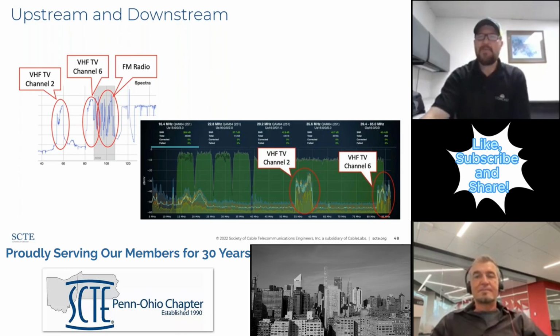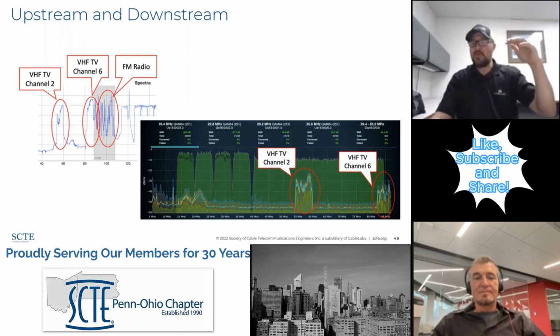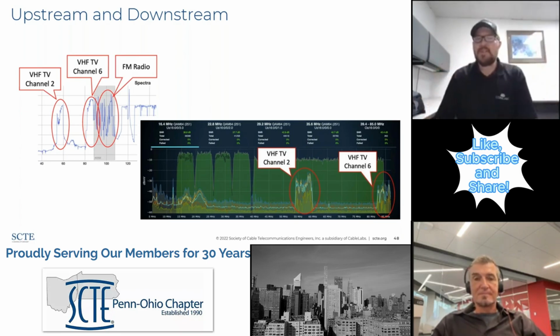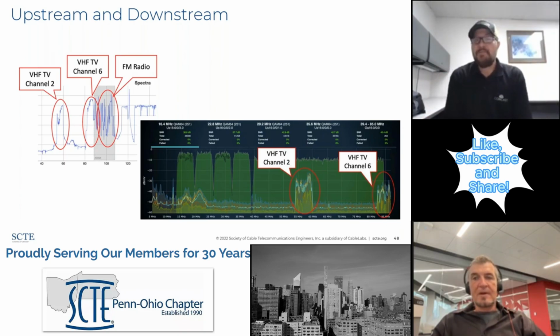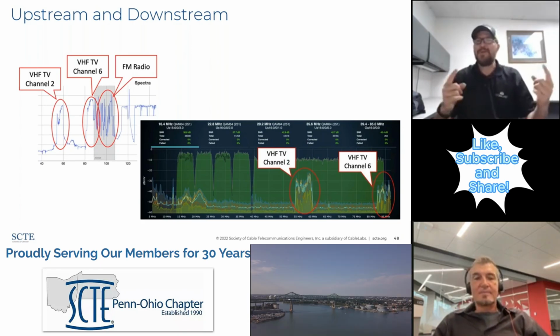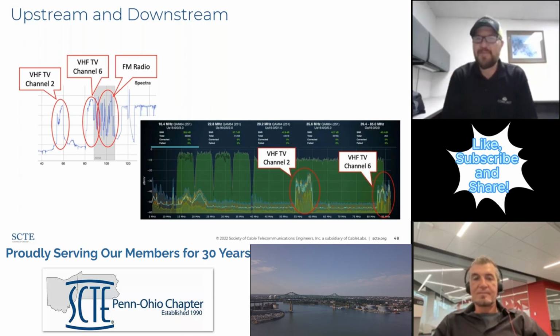So while the symptoms are different, right, we're looking at from the upstream and the downstream perspective, the cause is the same. We have an over-the-air signal source and a shielding defect in the cable that allows those over-the-air signals to be coupled into our center conductor. And so in this particular scenario, if we were to find that shielding defect in the cable network, we could solve an upstream and a downstream problem with the same repair.